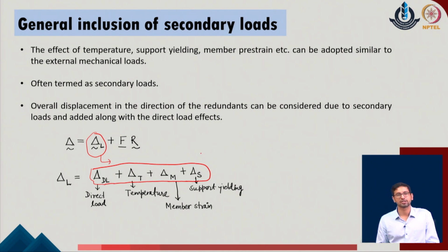Typically, these effects are considered as the secondary effects, and we have already seen that statically indeterminate systems have considerations where these effects can introduce internal stresses as well as internal resistance in the given members, and that needs to be accounted for, which is not similar to statically determinate systems. Now, in order to define these individual terms, we consider that the overall displacement in the direction of the redundants which has been calculated will now be adding the contribution of these components with respect to the temperature, member pre-strains or the support yielding in the given system as well.